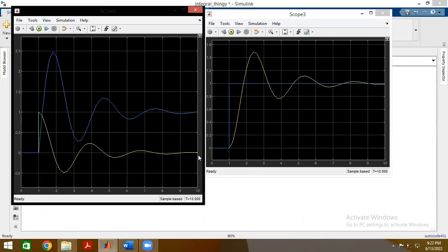Okay. So what do we see here? We see that over here, our error was 1, obviously, and our maximum drive signal to the plant occurs at the 0 crossing. And because the error now goes negative, it essentially means we're overdriving this plant. And this is why we see an overshoot over there. And then we try to compensate because we're seeing that the area under the curve is now negative. So in order to undo that negative area, let's go positive. But we overdo it, and that's why it undershoots.